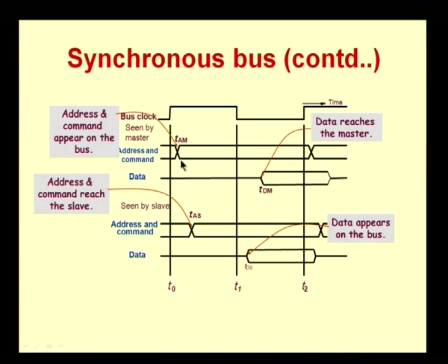Okay. This is when it will actually appear on the bus. It will appear on the bus and, as we said, it will have to stay on the bus for a little time after the data has been strobed in. You can see that this value remains on the bus until the end of the clock and also for a little bit of time after the clock. That is what you need to remember over here. So, this is the placement of the address and data, address and command.